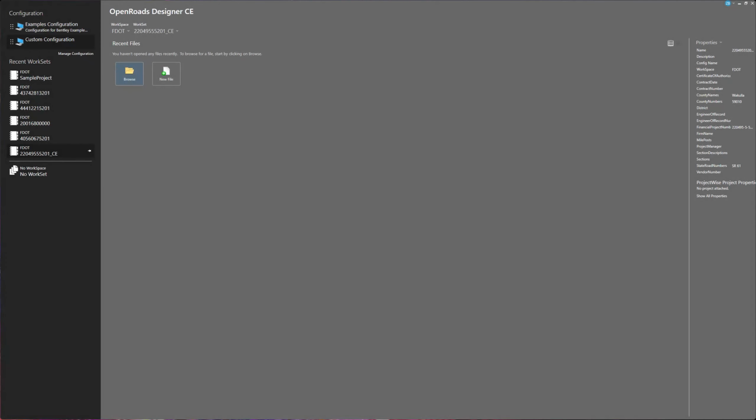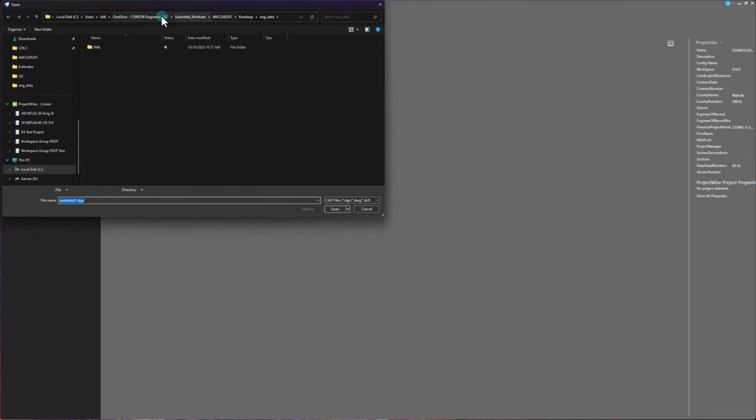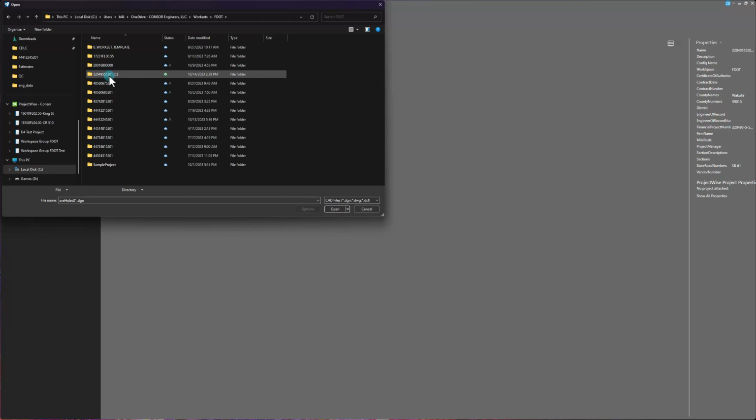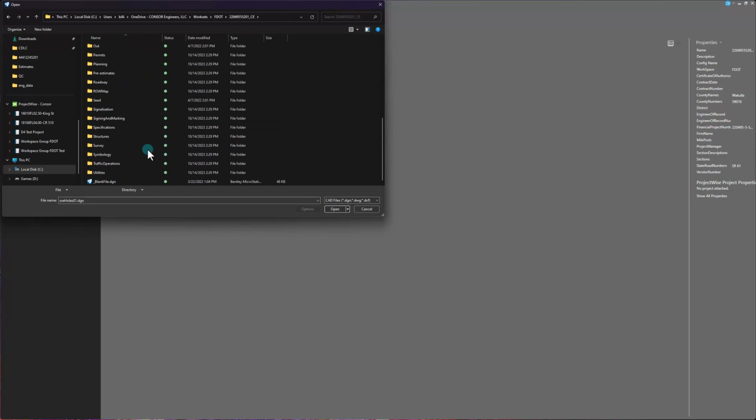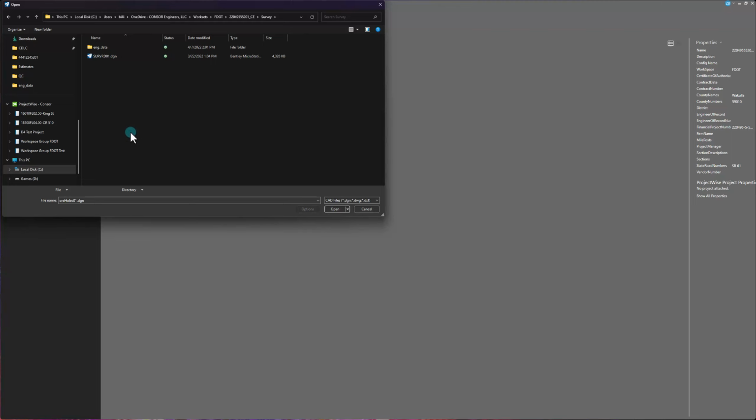Hello everyone, today I'm going to make a video on how I would start a brand new project. I've got FDOT's sample project up right here, and there's really nothing in this project. So what I want to do first is navigate over to the project, your normal directory, and the first thing that you'll probably receive from a surveyor is this SURVRD01 file.